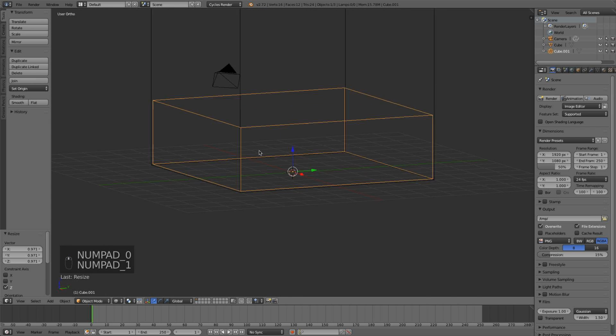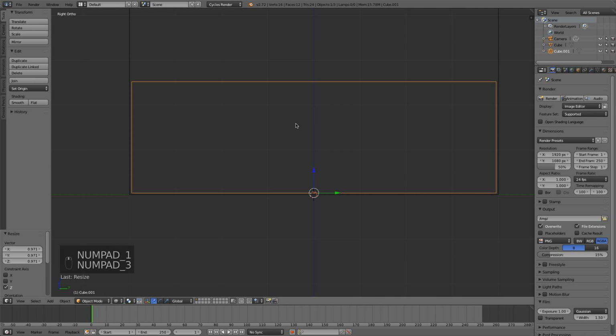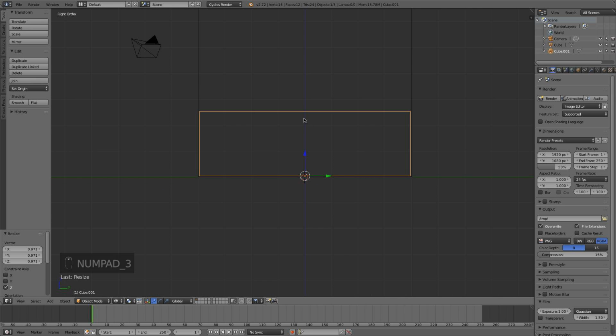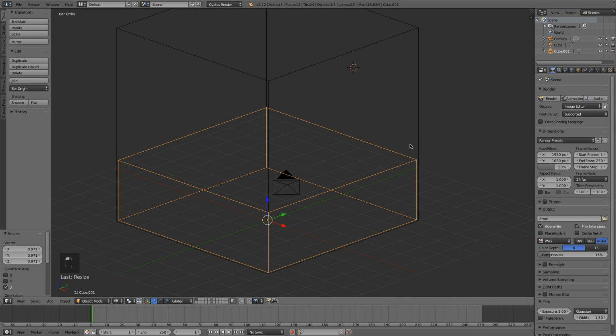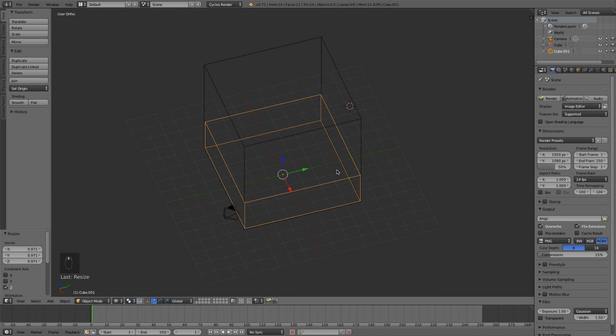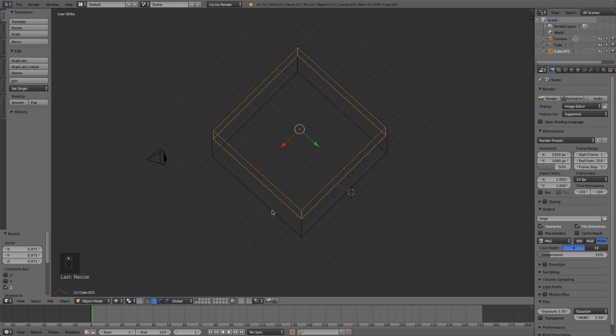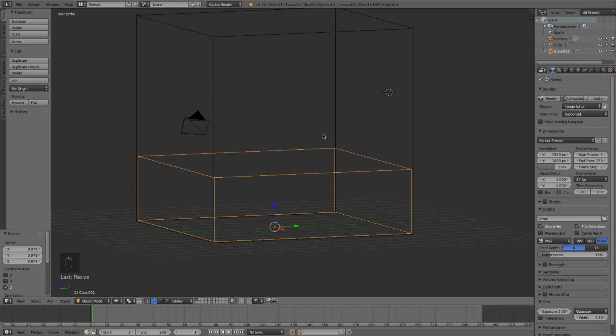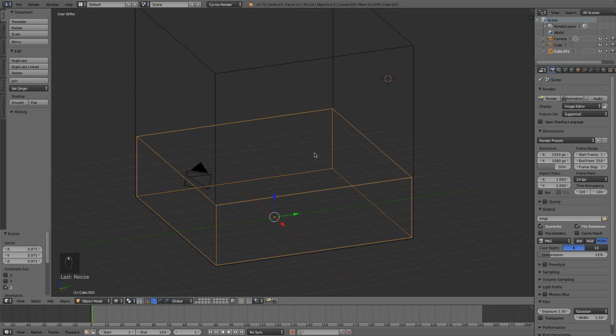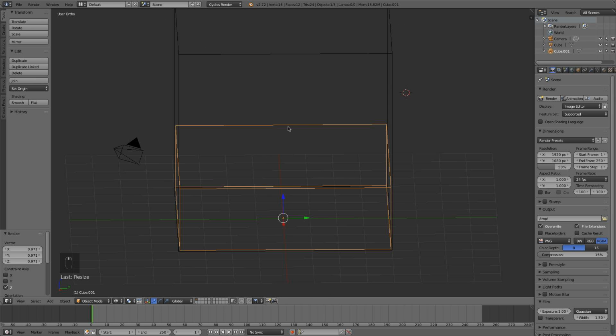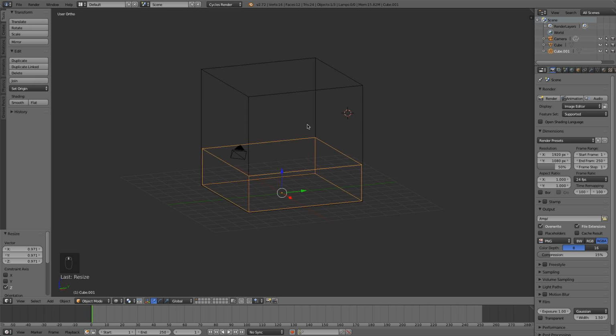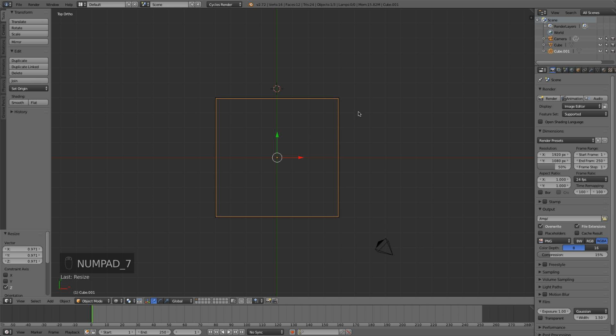Very good. Now we need an obstacle to collide with the water mesh. So I used a few different obstacles, and you saw in my quick examples that I used a football and I used a beach ball. Now if you want to use a football, you can use that tutorial that I just posted last week on creating a football in Blender, and that will work nice. Or you could do what I'm going to do here and just create a basic UV sphere.